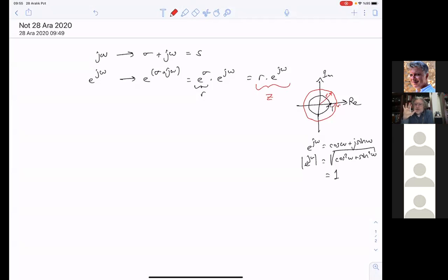So we will just notate it by Z. And the transform by using a certain value of, or a free value of R will be called the Z transform. Instead of the discrete time Fourier transform, we will shrink down the expression to become the Z transform.